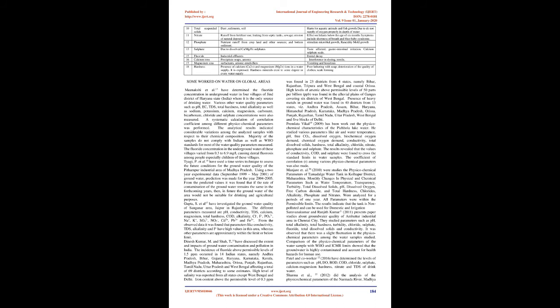13. Sulfate: due to dissolved Ca, Mg, Fe sulfates; taste affected, gastrointestinal irritation, calcium sulfate scale. 15. Fluoride: industrial effluents; dental decay. 16. Calcium ions: precipitate soaps; interference in dyeing, textile. 17. Magnesium ions: surfactants, anionic emulsifiers; vomiting and laxative effect. 18. Hardness: presence of calcium, Ca2+, and magnesium, Mg2+, ions in a water supply. Hardness minerals exist to some degree in every water supply; effects include poor lathering with soap, deterioration of the quality of clothes, and scale forming.